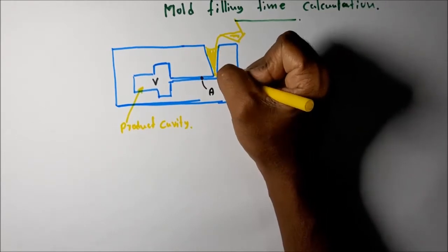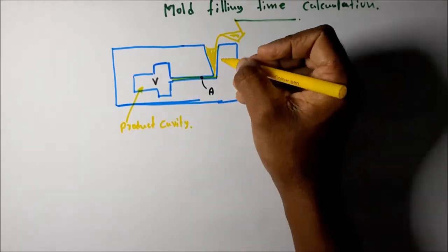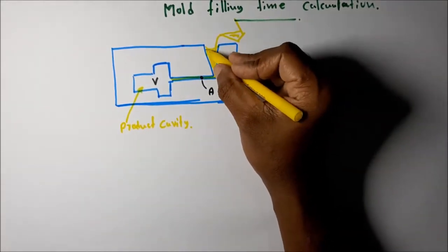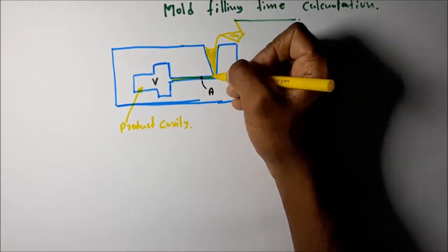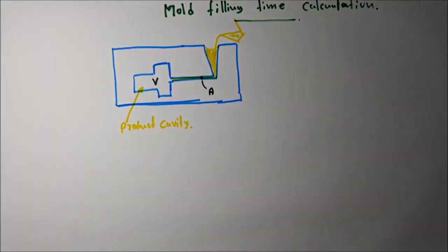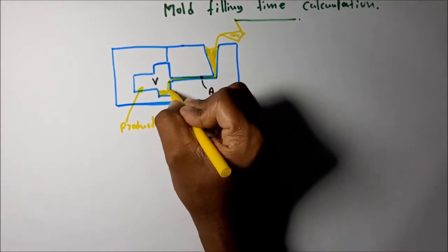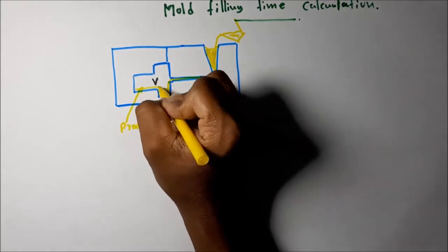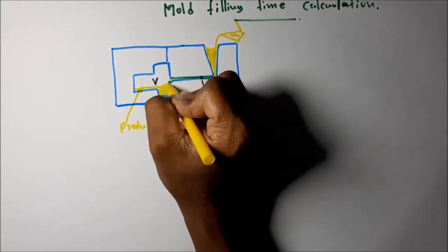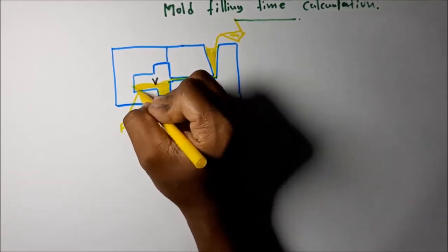Then this molten metal passes through the main runner to the cavity because of the gravity force. Then the air trapped in the cavity escapes through the vent hole. This is what happens in molten metal pouring. As the mold gradually fills, the air trapped inside escapes through the vent hole or open risers. If an open riser is there, the air can escape through it.